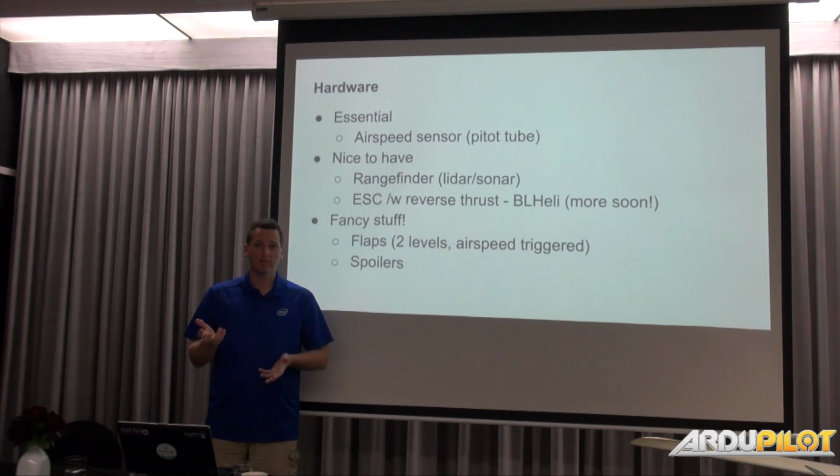They're generally heavier and more powerful and that sort of stuff. We do have the ability to power down the LiDAR when you're above certain altitudes or when you're not landing, so that's a helpful feature. I've seen problems with LiDAR where it would actually jam your GPS or cause other noise issues. So when I fly, there's a pin you can use to actually power down your LiDAR. I've been flying a lot with the LiDAR Lite V3, which we've worked out the bugs on the software side to tolerate.